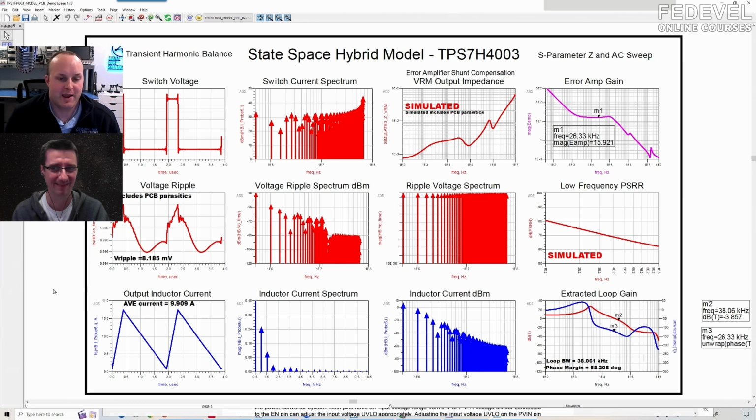And that's why we did this paper. This is why it's hard today to be an engineer. There's a lot you have to do, but here we're showing you it's not that hard, not that scary. It's not hard to build this model or to extract this artwork. And this is only 10 amps. Imagine what will happen at 100 amps. From an EMC perspective, you can see this additional energy in the spectrum. That's because of this additional periodic ripple in the output response that you don't want. No power electronics guy wants this.